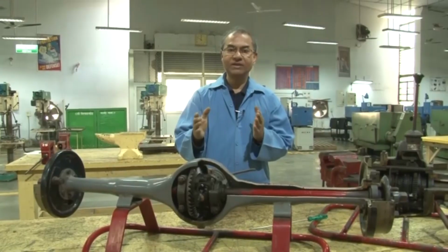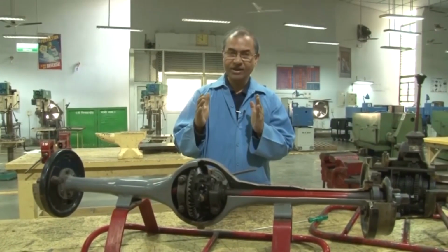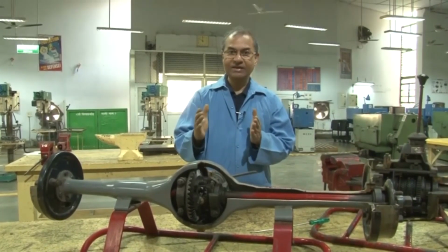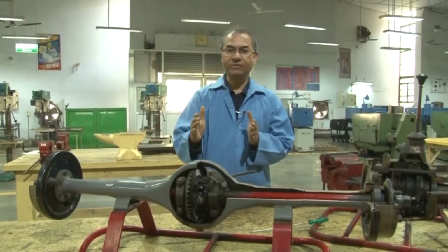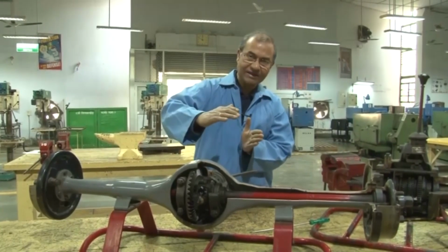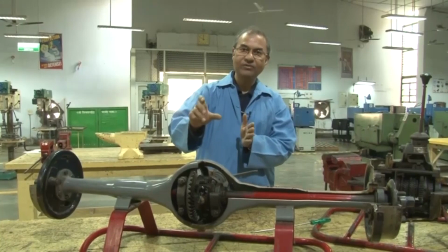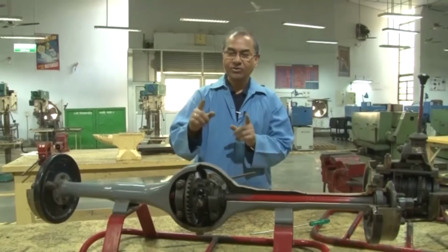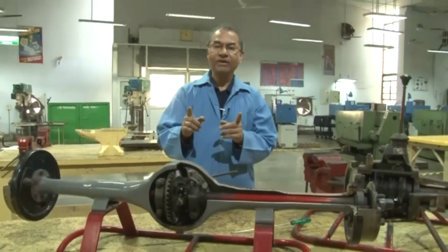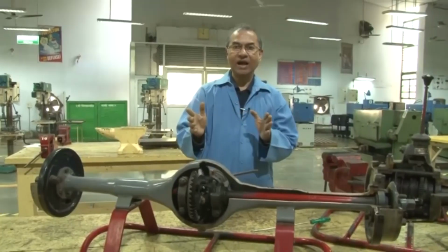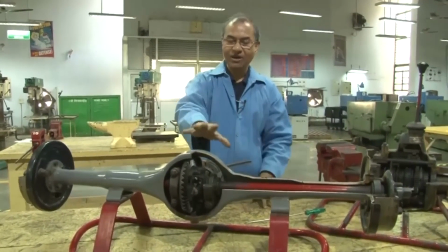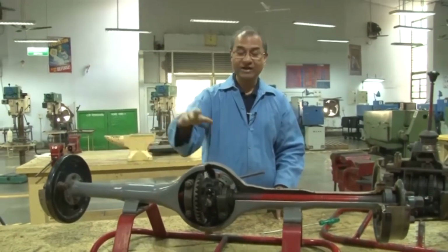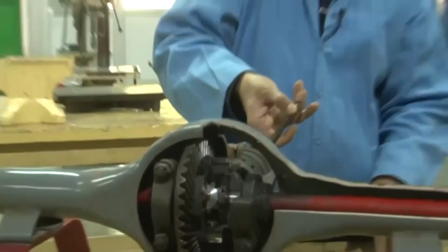RPM being the same because this is the internal combustion engine which is used, all right, and the diameter is changing. So, if the diameter is more, the speed will be more, and when it is taking a turn like this, the outer wheel will have a bigger diameter and the inner wheel will have a smaller diameter. So, then the speed is changing. Now, when the speed is changing and the RPM is the same, you have to have a mechanism so that these two speeds are different. That is why the mechanism is called the differential mechanism.